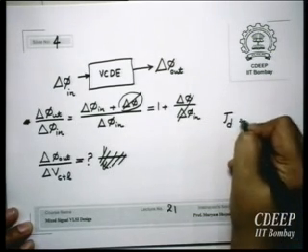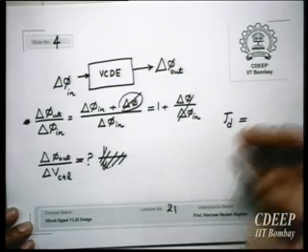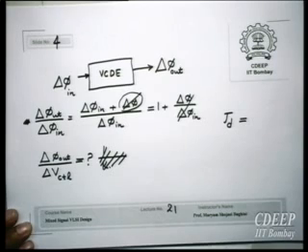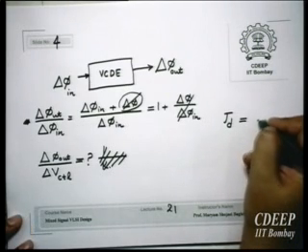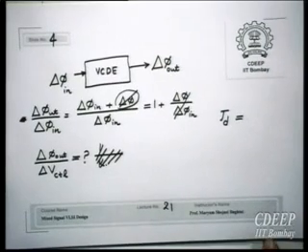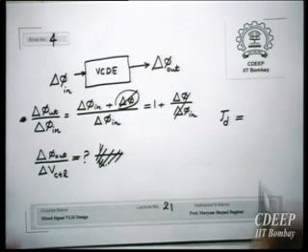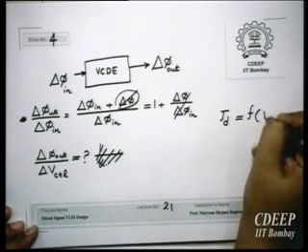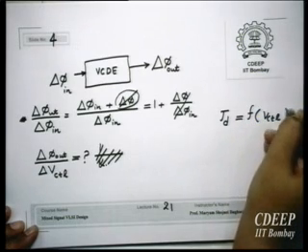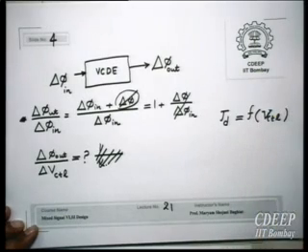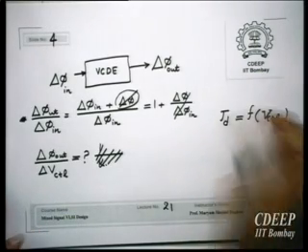This time delay is a linear function of voltage, assuming it is linear. Actually, it's not a linear function. If you remember, for the current-starved inverter, delay was not a linear function; frequency was. So it's not always linear. This is a function of VCTL. These are all large signal, so large signal is not linear.